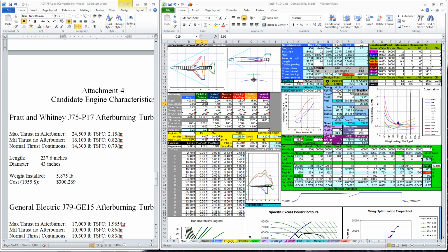The F-104 and the F-101 both had T-tails like this, and it didn't actually work out very well. At high angles of attack, the T-tail would get blanked out by the wake of the wing. The aircraft would pitch up and go out of control. So we don't really want that kind of behavior. So what the F-100 and the F-4 and T-38, various F-5, F-16 do is put the horizontal tail down low. So let's move it down low.